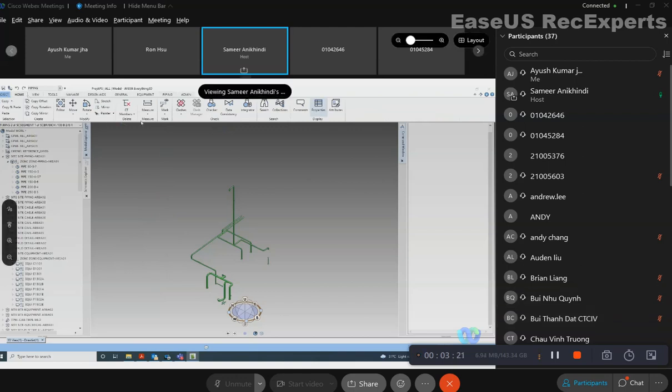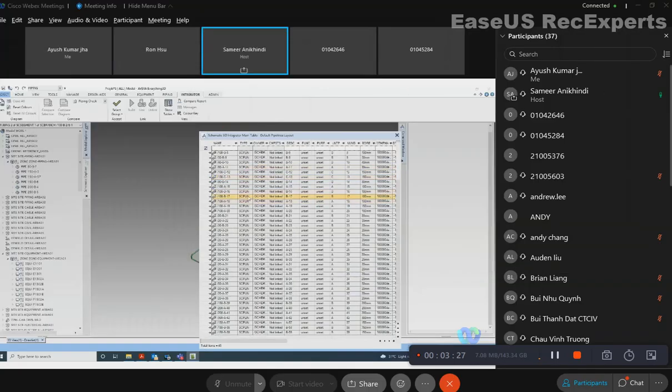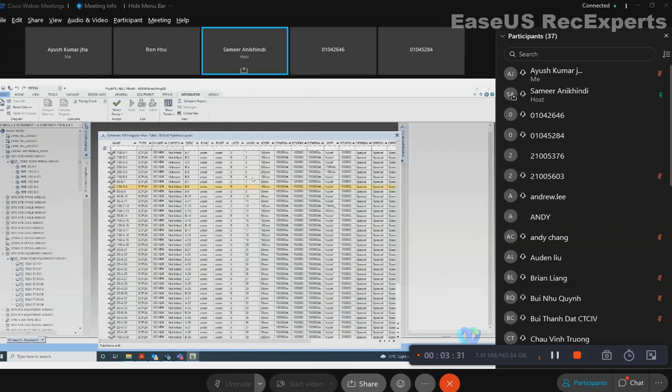Go to Home tab, Integrator mode. It will give you one window. So you have to set the pipeline as the current element. So right click at the top of the columns, anywhere on the top of the columns, main object type, set it as pipelines.